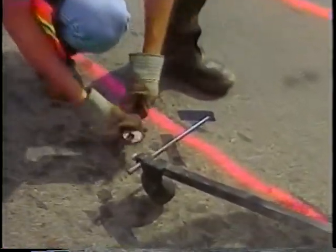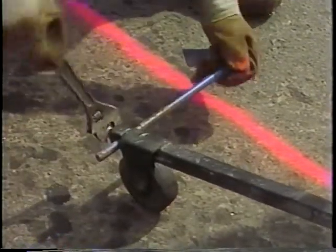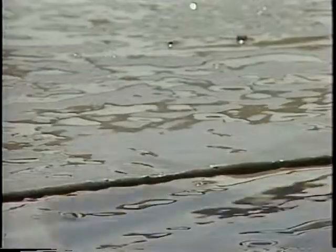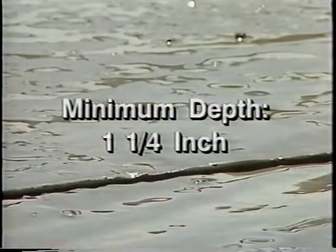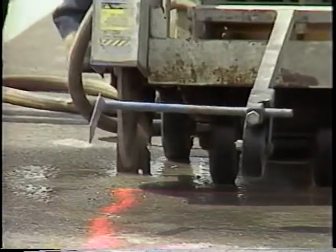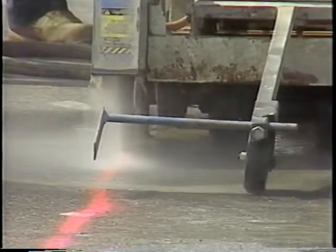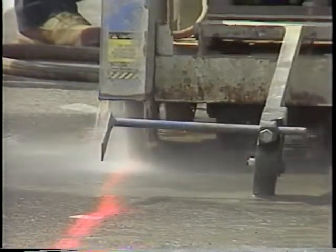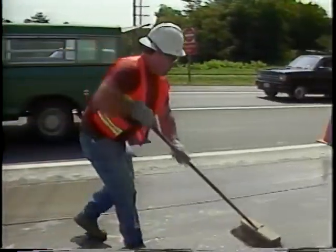Regardless of the type of saw used, it should be equipped with a depth gauge and a horizontal guide to assure proper depth and alignment. Check the depth of the saw cut frequently to assure that it is constant. Although the appropriate depth depends on the number of turns of wire, a minimum depth of 1 1/4 inch and a maximum depth of 2 inches should be maintained. If your saw cut is out of alignment, do not make a second cut near the first. If a second slot is necessary, cut at least 4 to 6 inches from the original slot to avoid significantly weakening the pavement.